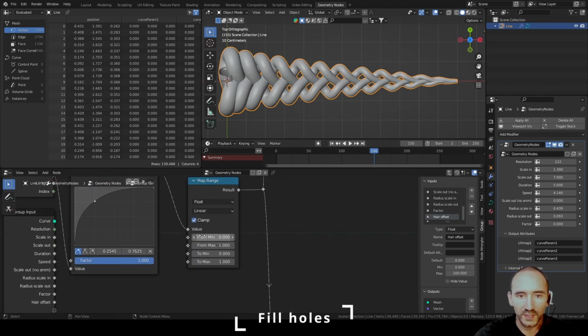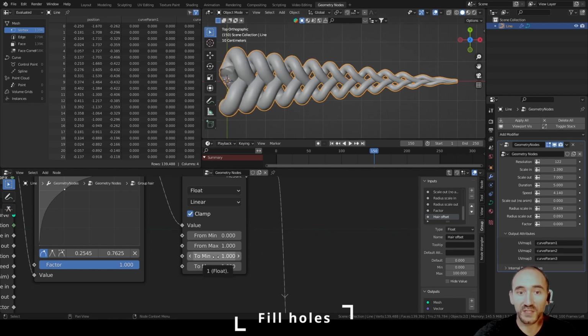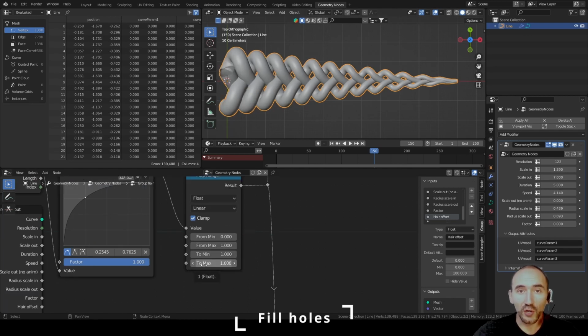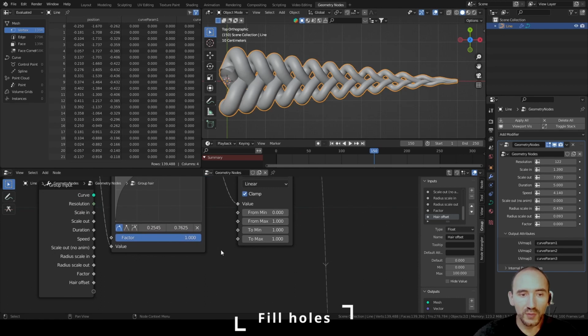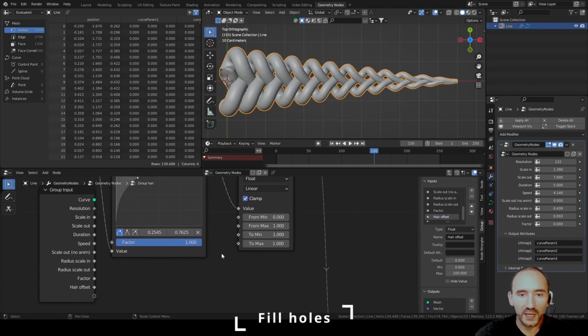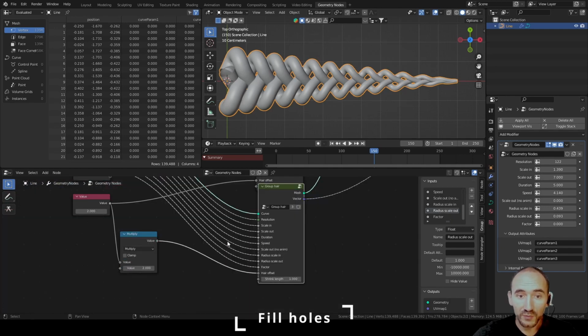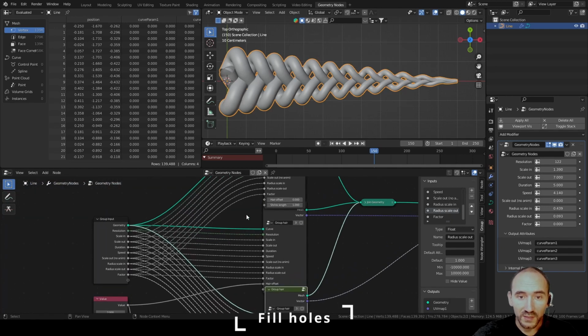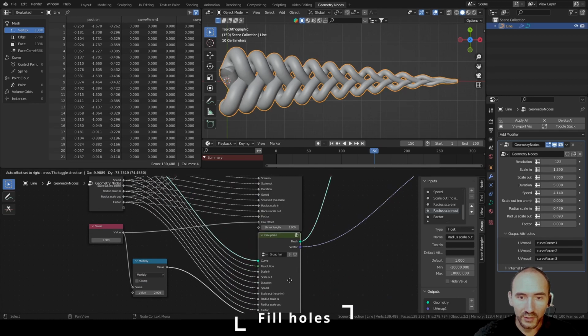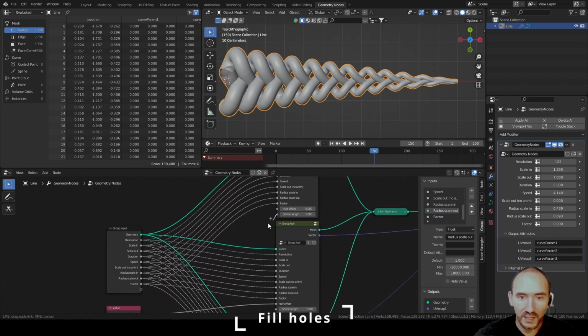So we want a coefficient of 1 at the start point, and at the end of each curve I want a value that I can export to my group. So I can rename it to shrink length. It's obvious I have to press Tab to exit from this and link the new parameter outside.